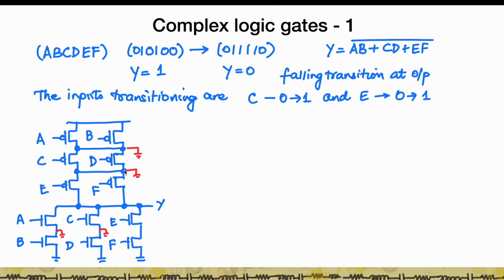So we know that when you're going to do the transition delay, we are worried about where these intermediate nodes are. Are they close to 0 or not? So for example, if you look at A, it is always at 0. Now when A is always at 0, this node sitting here is always at VDD. And remember, we are looking at a falling transition. Similarly, if you come here, I've chosen A and B in this way so that B and D are closer to ground.